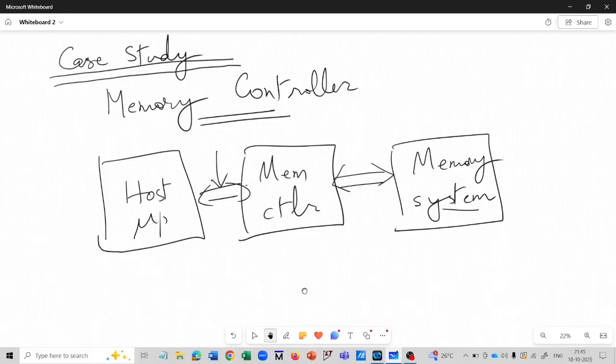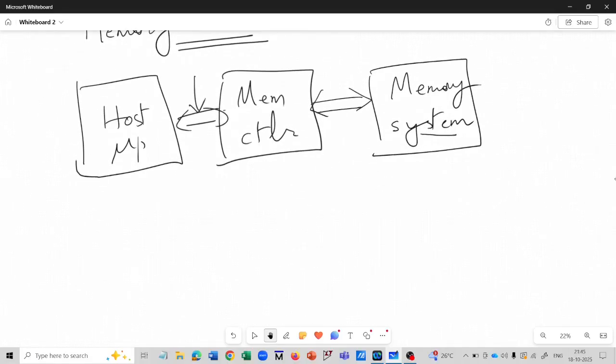The important feature that interests us is that the latency of the memory system is not predictable. If a particular address is available in the local cache memories, then the data may be available in one cycle, or if it is not present, it will take several cycles or maybe hundreds of cycles, which means that we need some kind of handshaking through which the availability of data will be indicated.